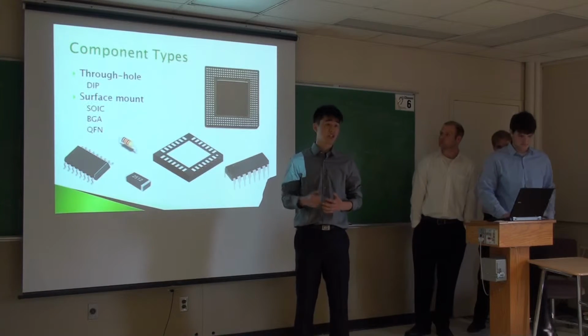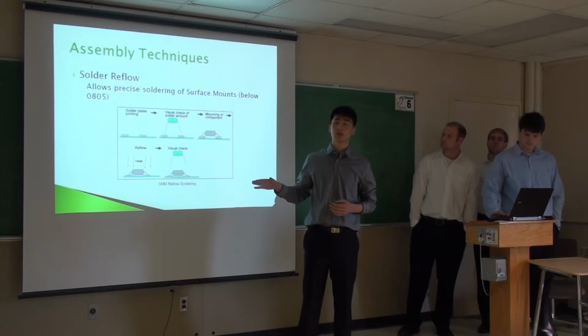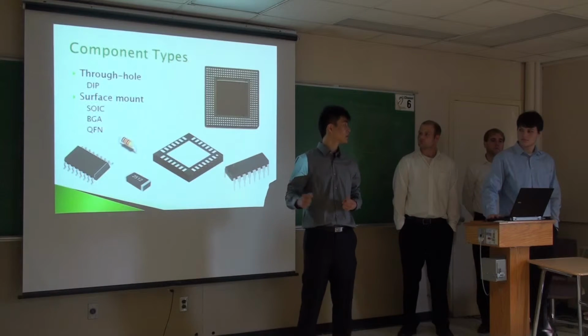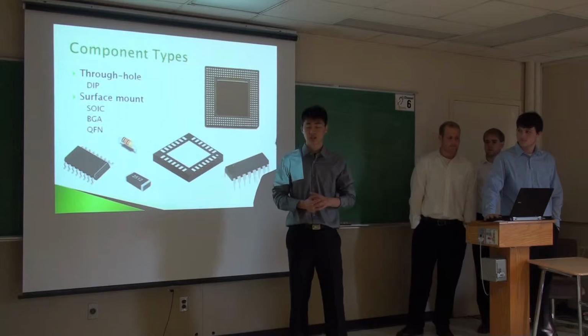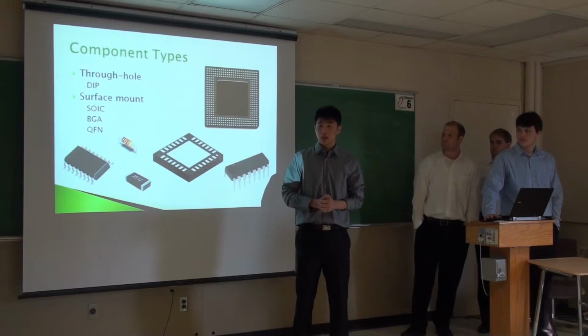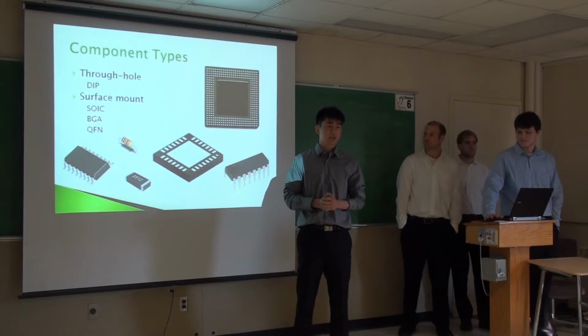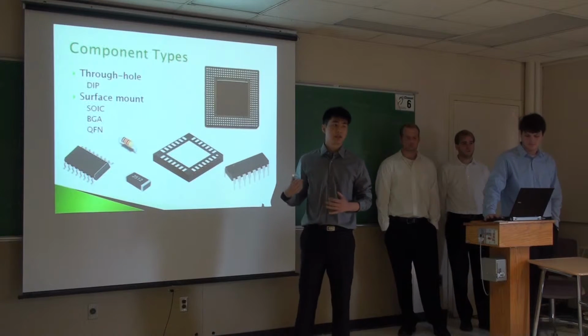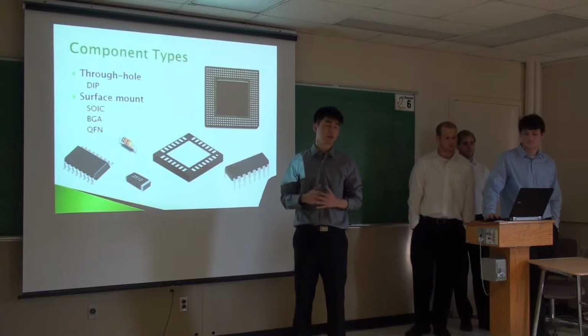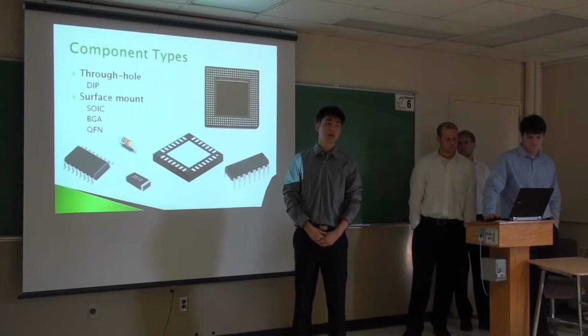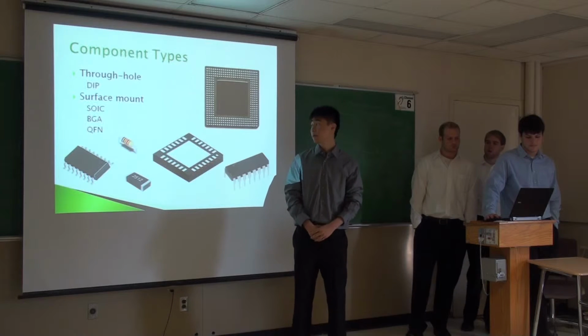Another choice of IC is SOIC, which stands for small outline integrated circuit. It is a surface mount type of the DIP. The difference is bending lead, thermal characteristics, and occupying less area than the equivalent of DIP.